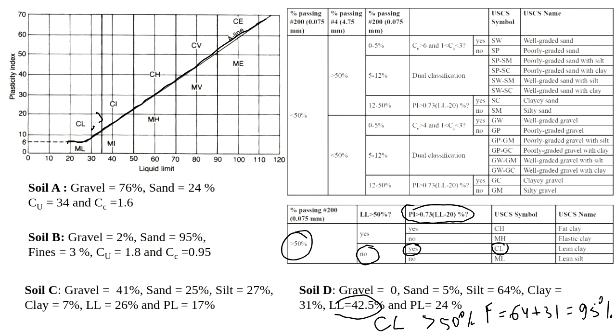It's below the plasticity index. Plasticity index it's 18, right? So yeah, it should be above. So we have plasticity index which is greater than 16.4. So it's above. Yes. So it's going to be clay. Okay. So we figured it out.